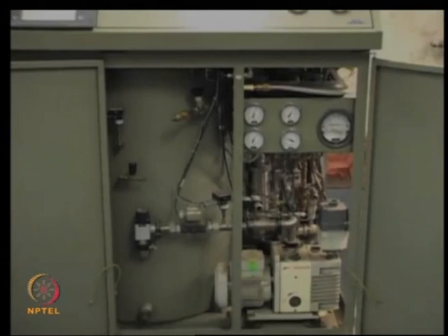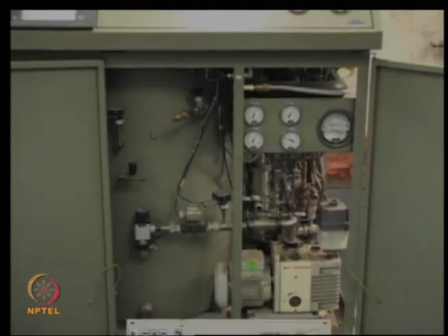The entire liquefier works on the Collins cycle. So, you know that there are 5 or 6 heat exchangers, and there are 2 reciprocating expansion engines. Alright. So, this is a cold box which houses all the heat exchangers and the expansion engines, and there will be an inside dewar, an outside dewar, and there is a vacuum in between with insulation. And whenever you want to start the plant, the vacuum will be made first, so that the vacuum is always maintained over there.